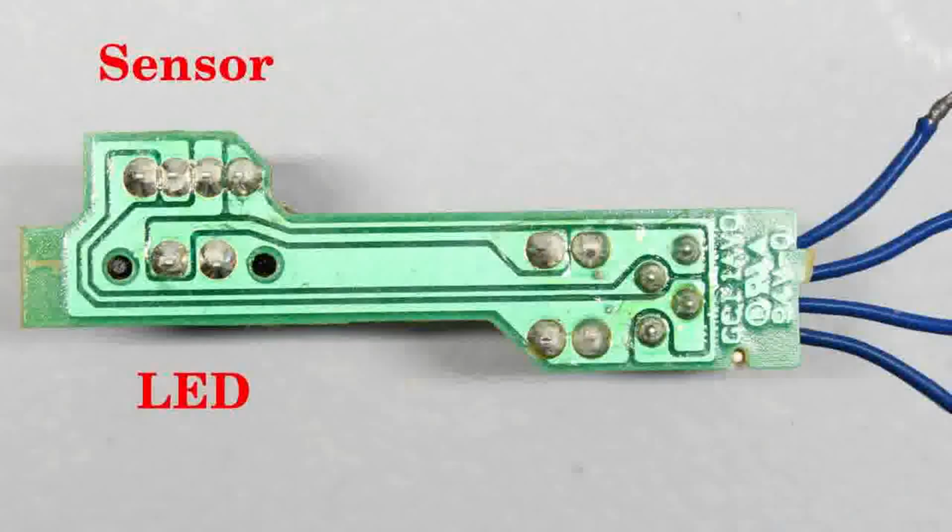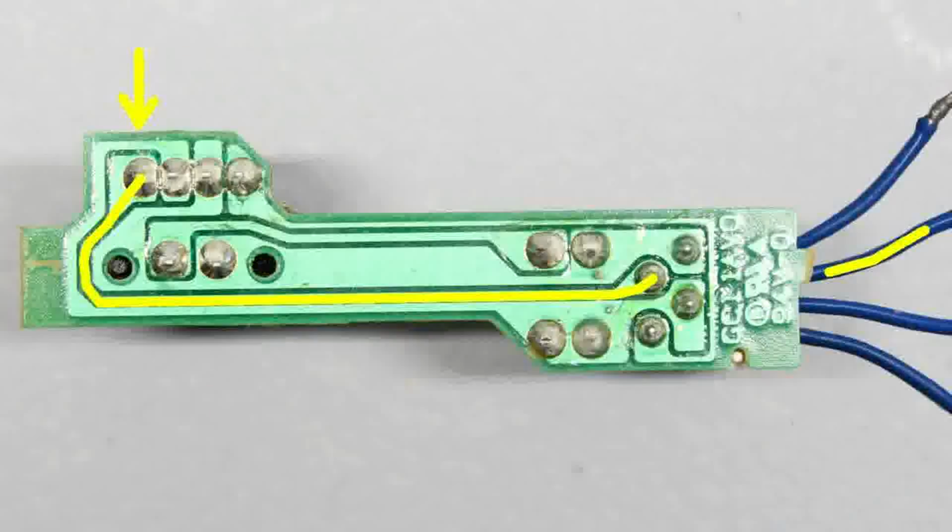Usually the sensor unit is soldered on a tiny extra board with just a few tracks on it that are easy to follow from the plug to the sensor, thus you can guess the pin layout. The pins of the sensor outputs are joined directly with the plug. There are no branches nor are additional components soldered on their paths.